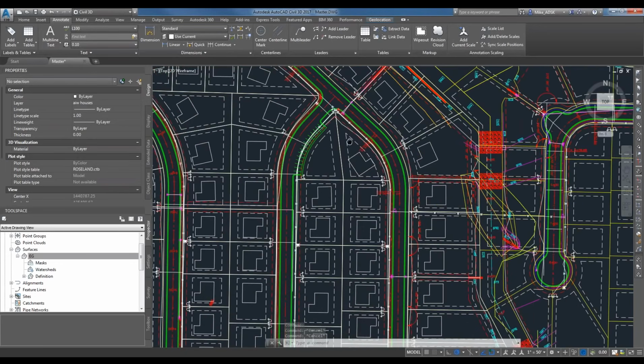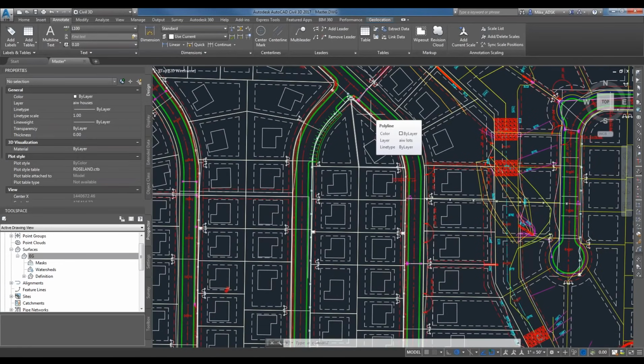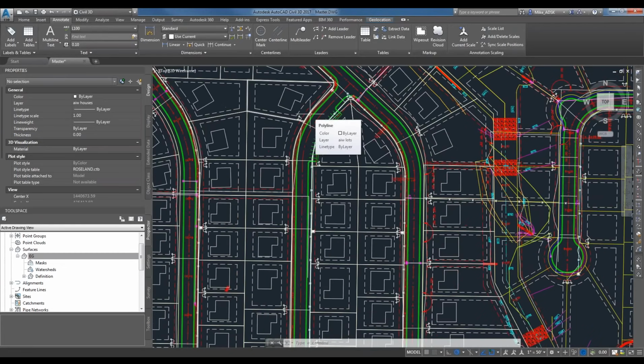So the cool thing about Civil 3D is that you can make corridors. Well, what are they? It's your roadway. That's really what the corridor is. It's split up into 3 separate sections: you have your horizontal design, your vertical design, and then your cross sections. Right now I'm going to start off with the horizontal design. Horizontal design is what's called your alignment. Alignment can best be thought of as your center line. If you're ever driving down a street and you have your double yellow line, you can think of that as your alignment.